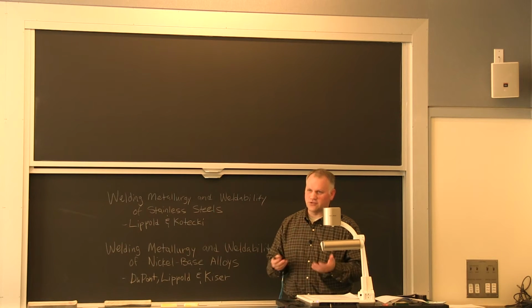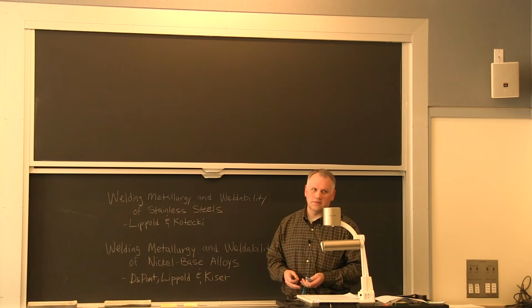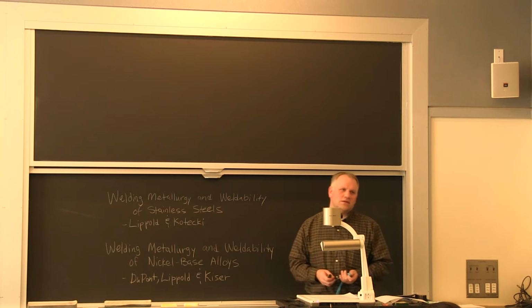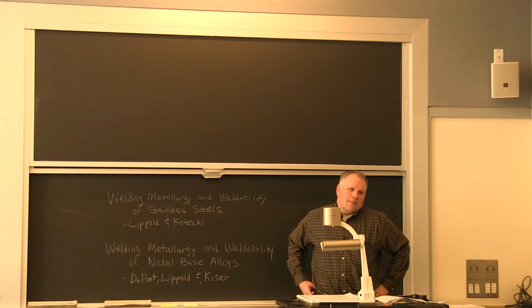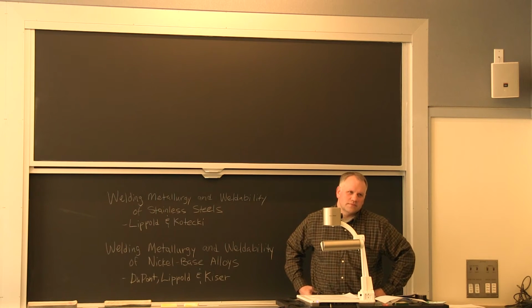I guess it does have to do with the amount of energy as well that it takes to come apart. But ductility is usually measured in elongation, stretch, at slow strain rates. Toughness is often referred to at higher strain rates, impact energies. Hitting it with a hammer.